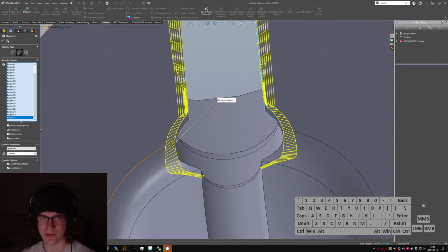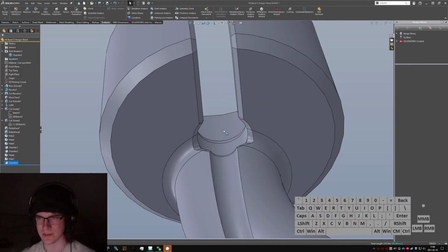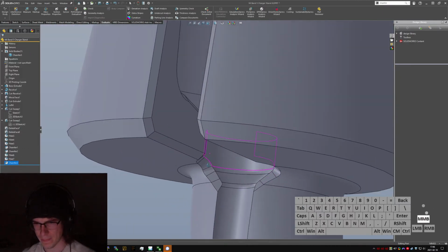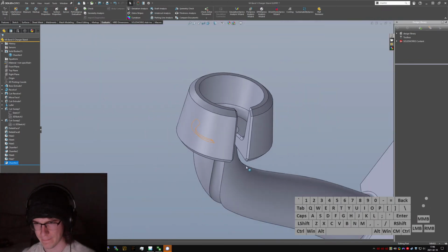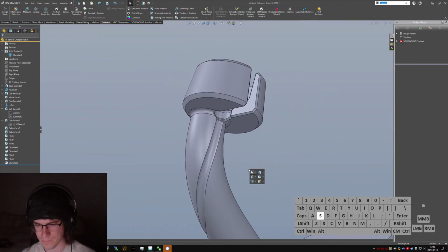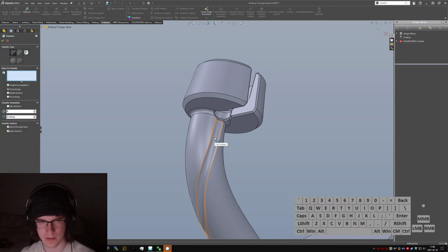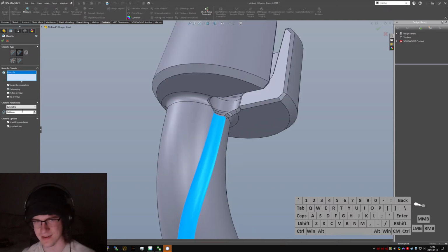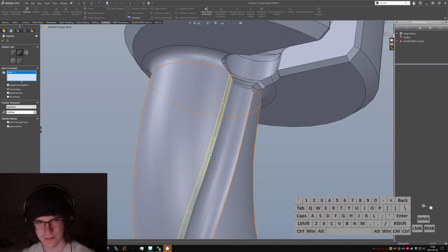That looks pretty close to symmetrical, and I think probably as close to symmetrical as I'm going to get. Now I just have to add chamfers on the back side here. These are going to be super short ones, too. Oh god, what have I done? I picked the face instead of the edge. Oh, it's going to flip out. Or not. Whack. Oh, and no tangent propagation.